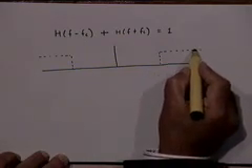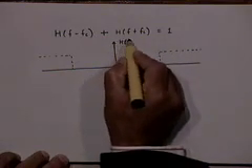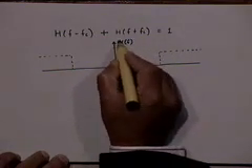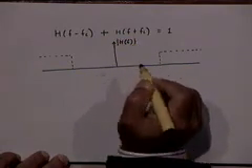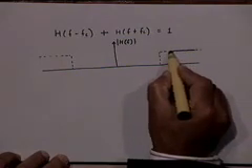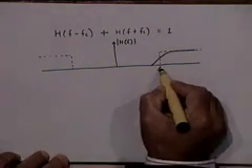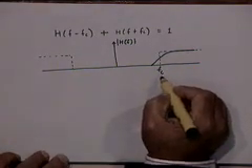The VSB filter on the other hand, so this we are plotting H(f), assuming it to be real, or you consider this to be mod of H(f). For the VSB filter, we had permitted that around the cutoff frequency, it have a gradual roll off, right?